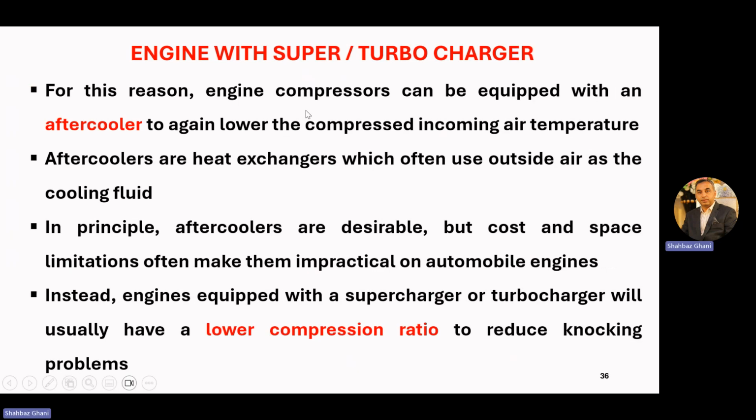For this reason, engine compressors can be equipped with an aftercooler to lower the temperature of the incoming compressed air. So an engine with a supercharger can be equipped with an aftercooler to lower its temperature. Aftercoolers are heat exchangers which often use outside air as the cooling fluid. In principle, aftercoolers are desirable, but cost and space limitations often make them impractical on automobile engines. It is a requirement, but due to space constraints and cost problems, we are unable to have an aftercooler in many of the vehicles having a supercharger.